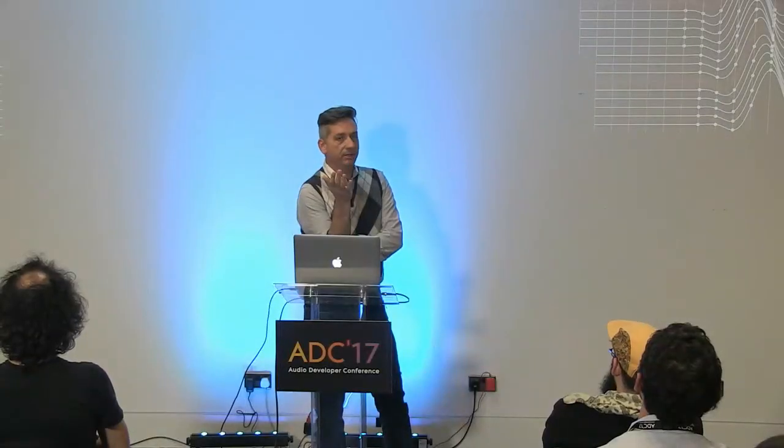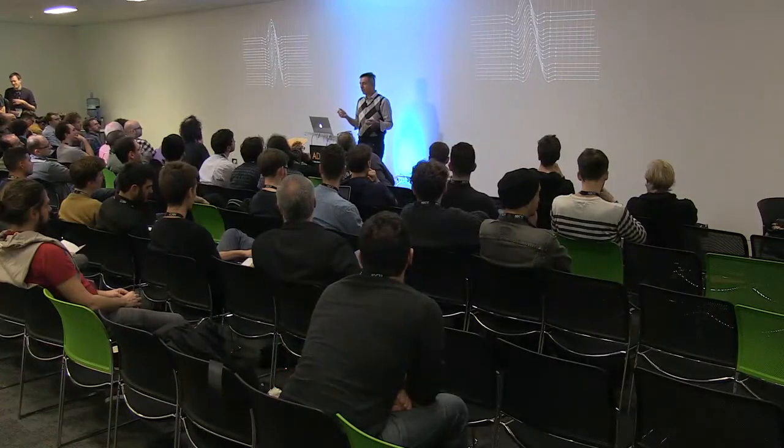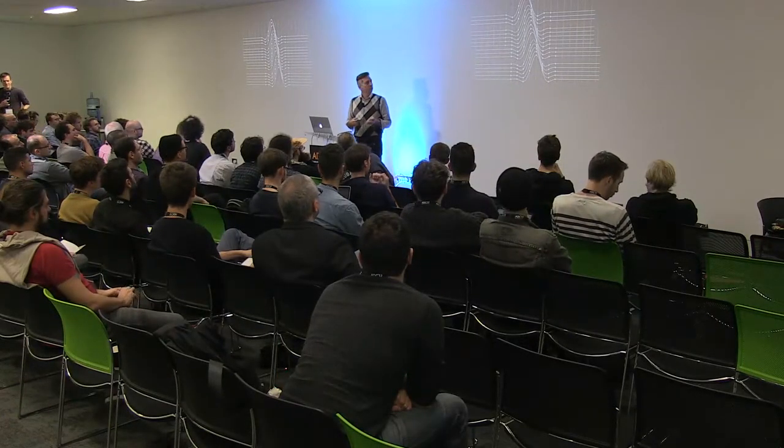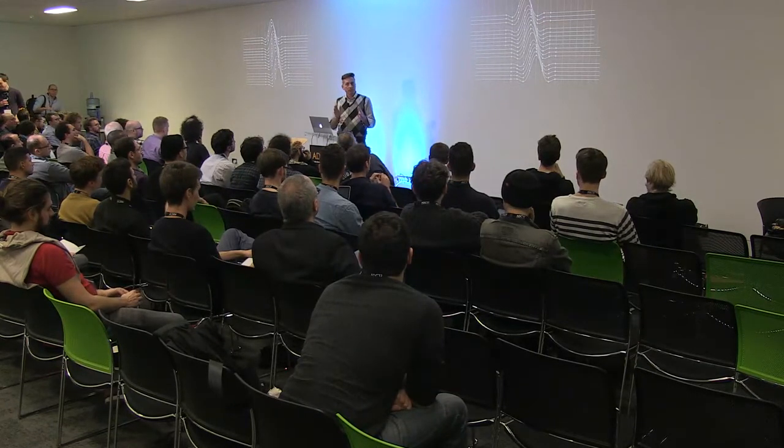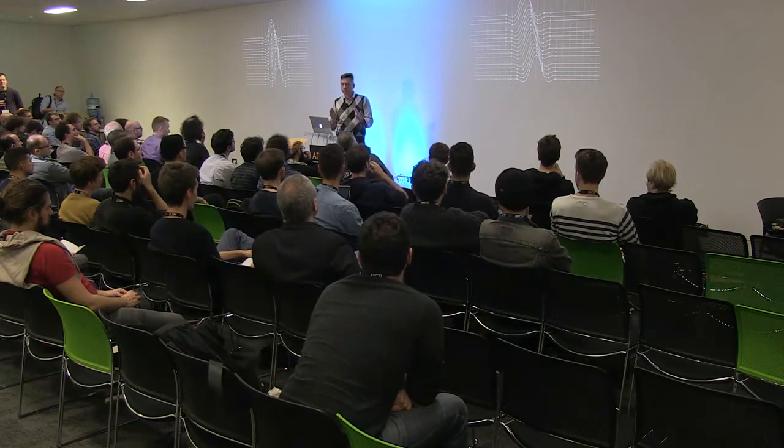So the good news is, for proper blitz synthesis, we need just a bunch of those pre-calculated blitz and put them in some array somewhere. And anytime we need an edge or a discontinuity, like in a square or a sawtooth wave, we just throw one of these into a tiny delay line.